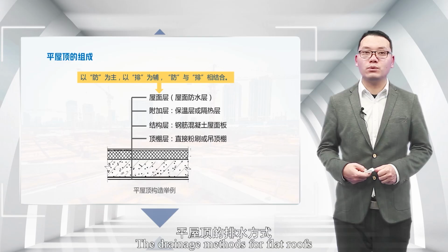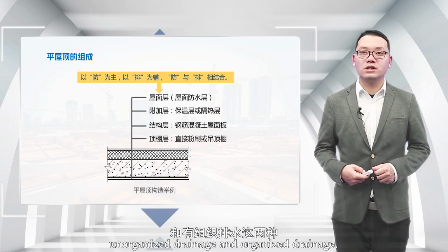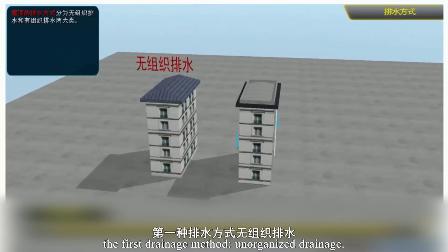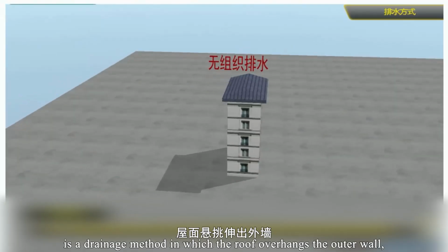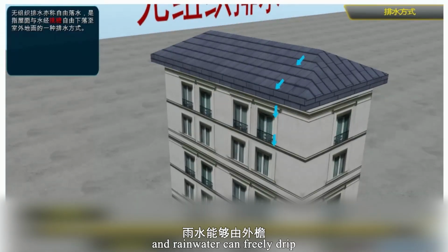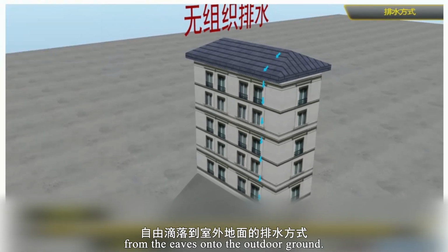Drainage methods for flat roofs can be divided into two types: unorganized drainage and organized drainage. Let's first understand the first drainage method, unorganized drainage. Unorganized drainage, also known as free fall, is a drainage method in which the roof overhangs the outer wall, forming eaves, and rainwater can freely drip from the eaves onto the outdoor ground.